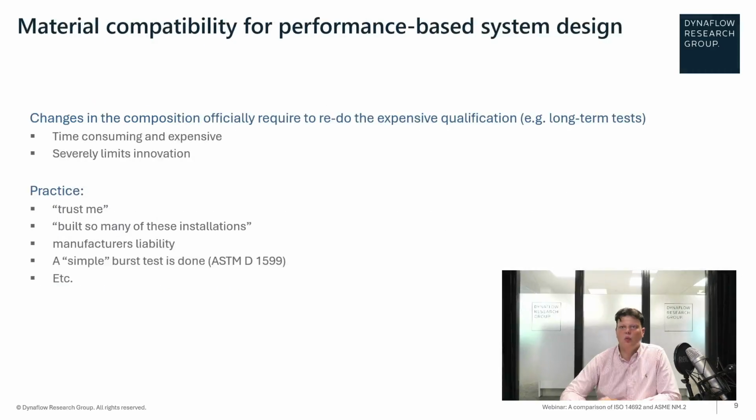Of course, when you have material properties which vary greatly between manufacturers and there's no set standard, this often means that there is expensive qualification to be performed. Long-term tests are especially time-consuming and expensive. Regression testing is at least 10,000 hours for one of those data points, and it can be a very costly endeavor for a manufacturer, especially if we're talking about requalification for just an existing product.